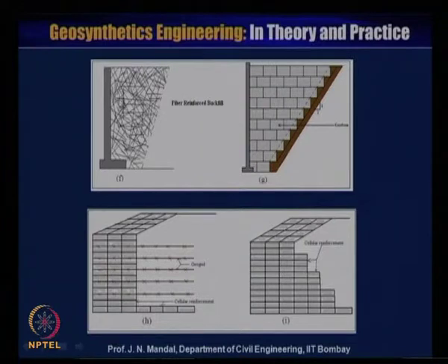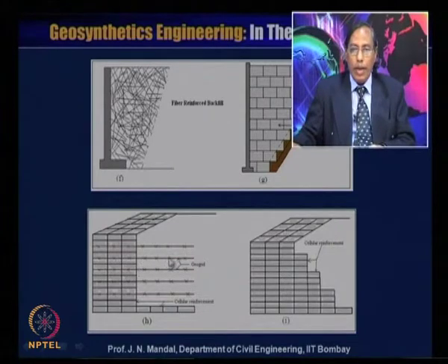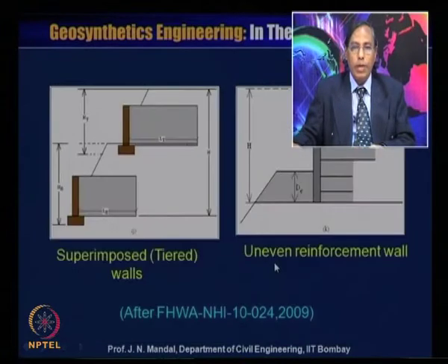Also geosynthetic material can be used with fiber reinforced backfill. You can also use the superlight material, that is geofoam, and you can provide drainage at the back. You can provide cellular reinforcement and the geogrid material. The cellular reinforcement will act as a facing element, or you can complete this reinforced soil wall using only the cellular reinforcement. You do not require any geogrid material.